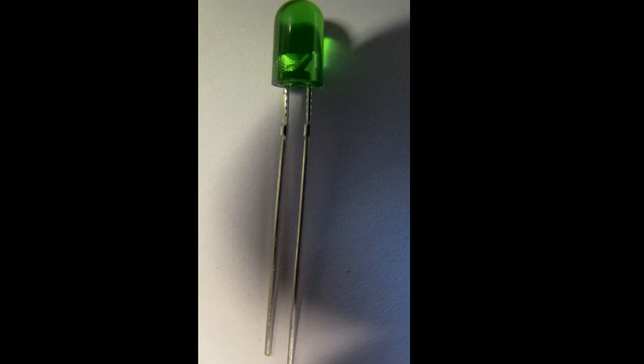On the right hand side you've got a very small piece of metal rising, and on the left hand side you've got a very large piece of metal coming up from the bottom of the case. These two lumps are connected together, kind of. I'll come to that later. They're called anchors, for a reason: to anchor the lead into the epoxy housing, solely to stop you from yanking the leads out and disturbing the actual diode internal to your LED.